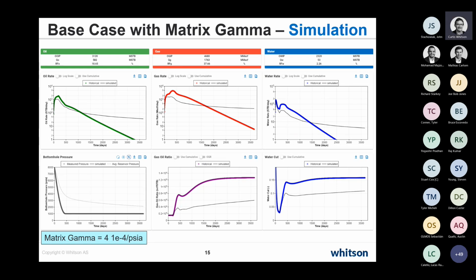Okay, you're talking about a global higher permeability throughout the drainage volume, not connected with pressure. Well, yeah, specifically in the matrix. But matrix throughout, not really pressure dependent, just having a higher perm versus a lower perm in your block of matrix. Exactly. So kind of a traditional question: what's the effect of permeability in a conventional, or even in a tight unconventional, if you just have 10 nanodarcies or 1,000 nanodarcies? You're expecting the higher permeability to have a lower GOR in general.